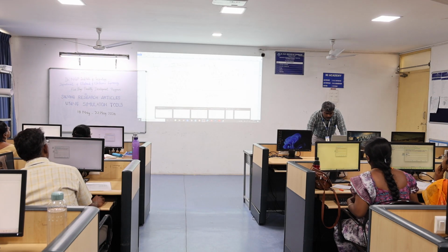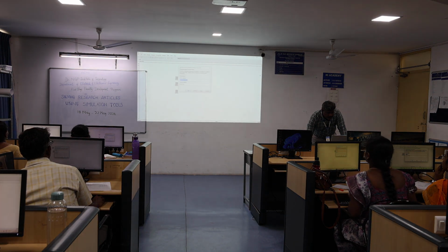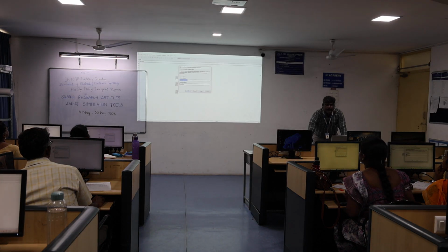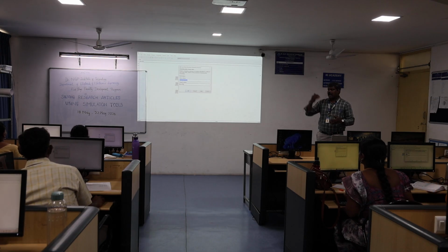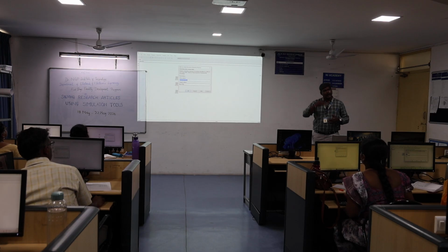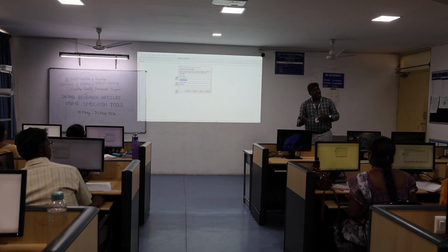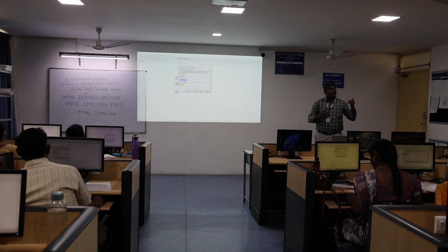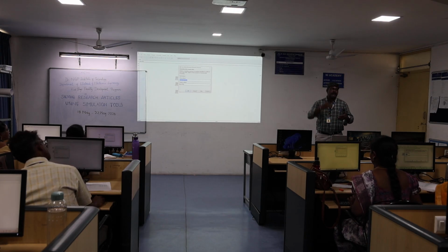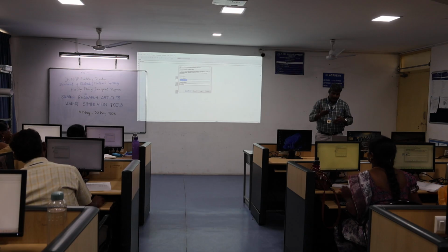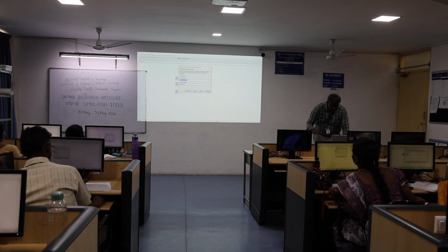In the Repeating Sequence block, for the output values you have to mention the magnitude values 0, 0.3, again 0, right? The second triangle starts from the starting value 0.3, next value 0.6, then again 0.3. Then the third triangle: the starting value is 0.6, then another value is 0.9, again return back to 0.6.